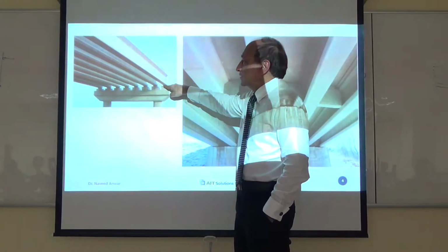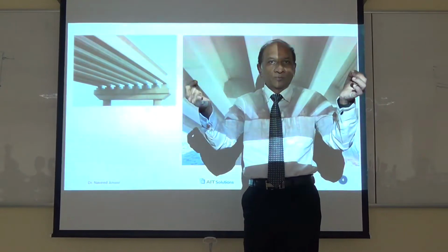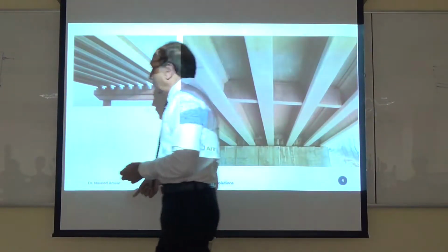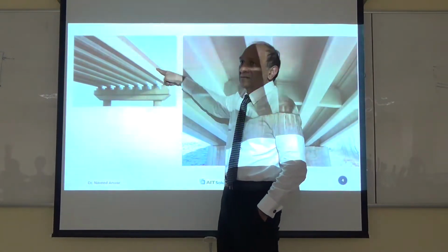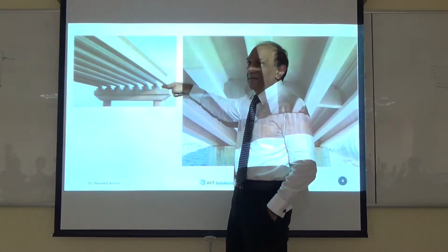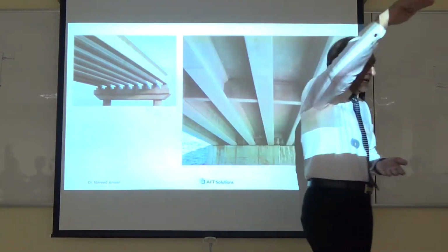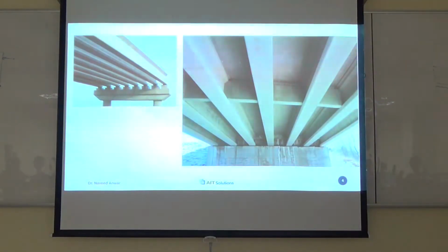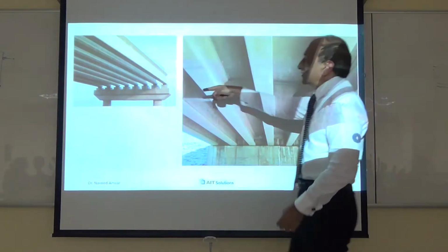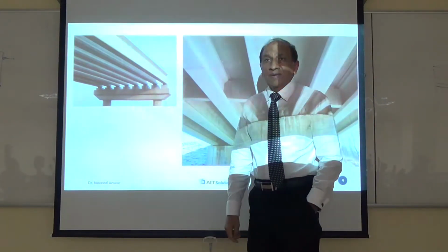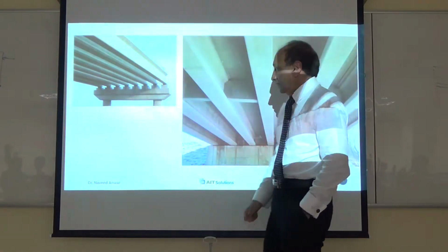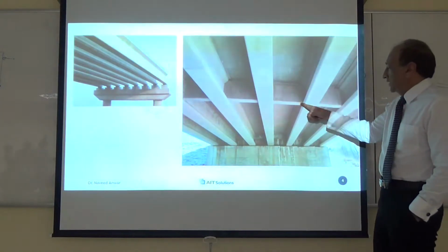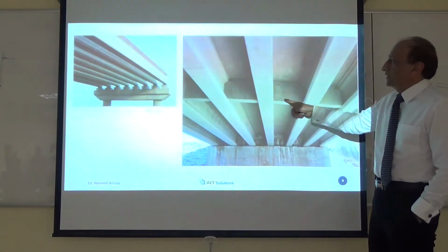So bearing is, if you draw a beam and put a pin support, you will see that will be here. Center line of the girder is here. Slab is here. Bearing is here. So the load is not applied to the center line and the support is not in the center line. They have a big difference between them. And this big difference can cause a major difference in the behavior. And then also we have to see how the diaphragms will affect that.